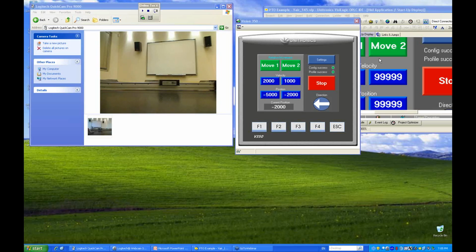And it can happen that when you download the application and change some parameters, something will go wrong. For example, you put in a jerk number which is higher than 16, or negative, or something like this. In this case you will receive feedback that something is not accepted, and with error codes you can get more information about what is not so good. So you can debug your application and put in the right parameters. Is this answer okay?